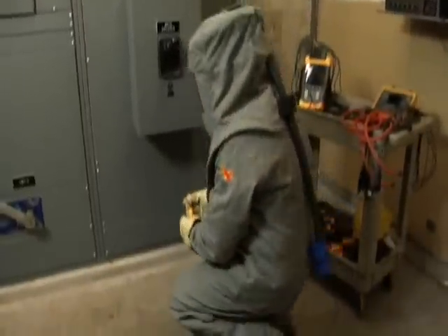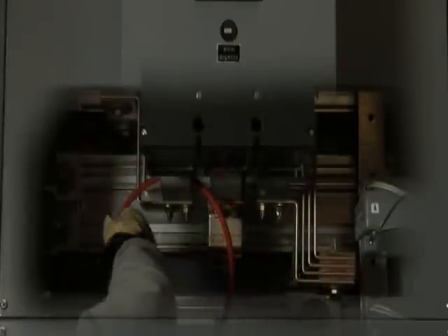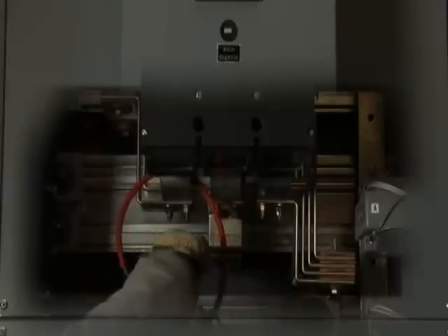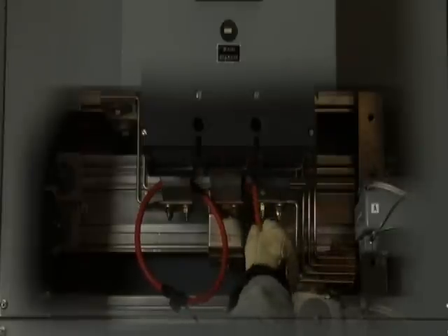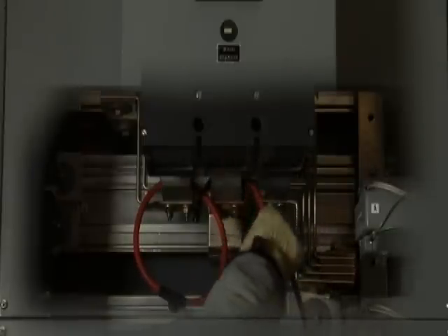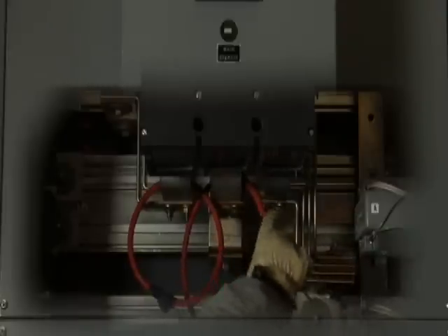Here you can see inside the main cover to show you exactly how connections are made. Be sure to connect leads to the proper phases and make sure the arrows on the current clamps point towards the loads. This is where color coding your leads can help. Connecting inside any live panel is tricky and is to be done only by qualified persons. Make sure you are using your voltage-rated tools in addition to wearing your PPE.